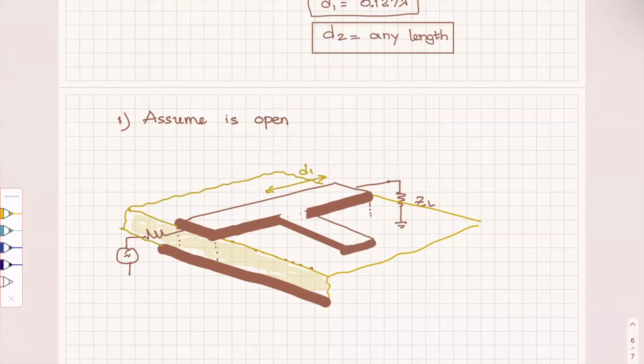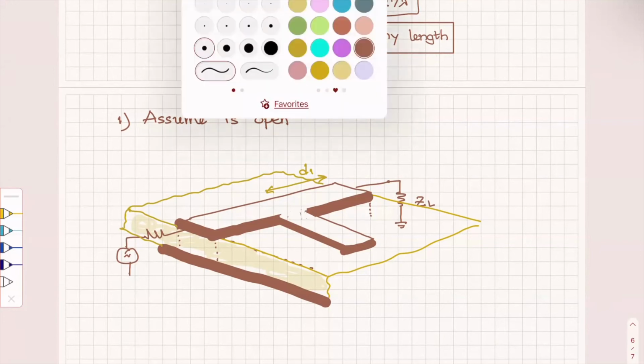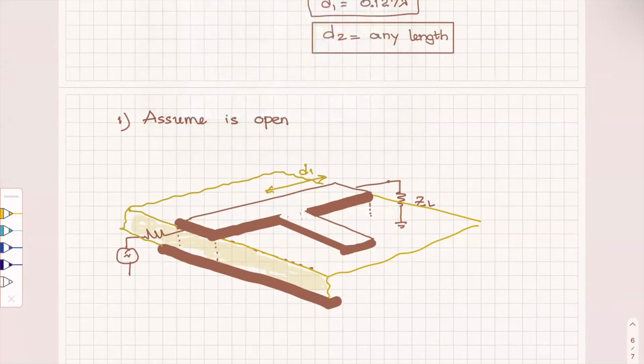Right, and then here, what I can do. Okay, can make a stub. That's how practically you do. That's what you do in this geometry. All right. Now, the stub is going to have the ground underneath it, but it's going to be open because the ground underneath it is separated from the stub. This is your stub. The ground underneath it is separated from your stub by the substrate.